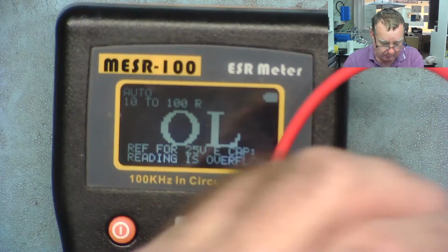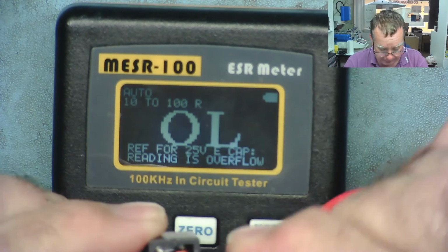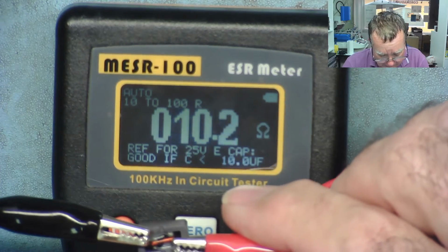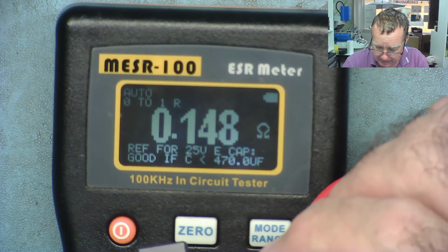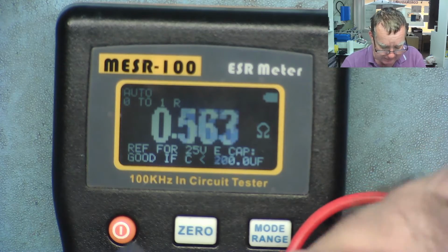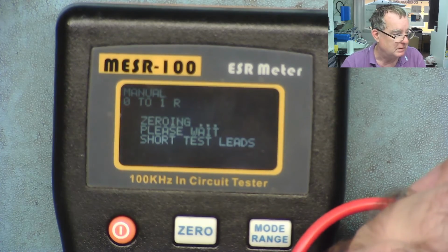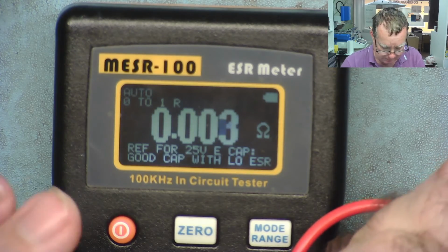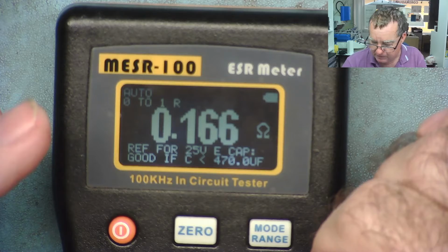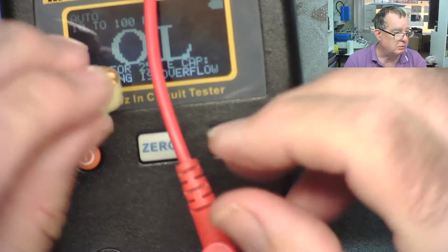Let's have a look at the other little one we have. So let's have a look at the smaller one. This is marked R30. So this is 0.3 of a microhenry. So again, we'll put it on the meter. We'd expect this to read lower. And it reads 0.148. Okay. I'll just make sure the meter is zeroed because we want to get an accurate reading of this. Yes, it's basically reading 0. I'll just press 0. Okay, it's pretty 0. Let's just try it again and see if we get the same reading. 0.166. Okay, so we can make a note of that one. 0.166.